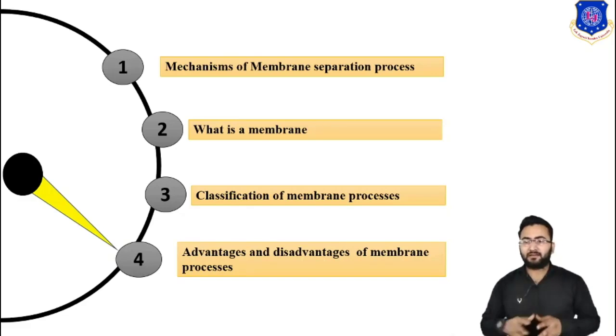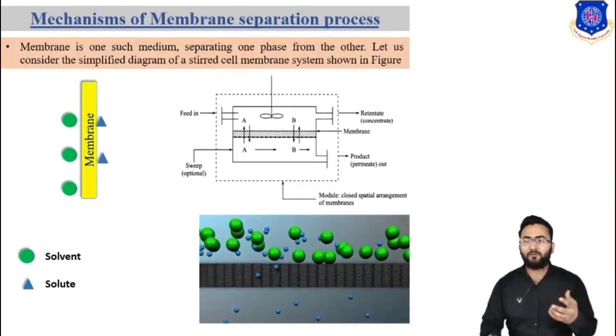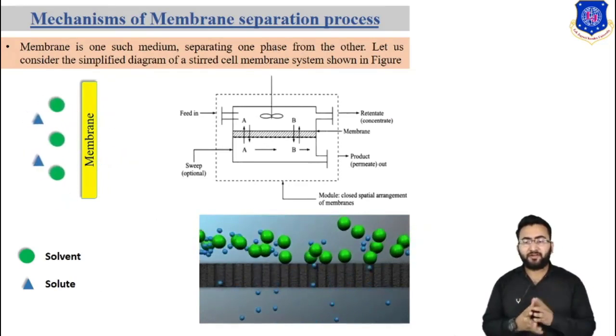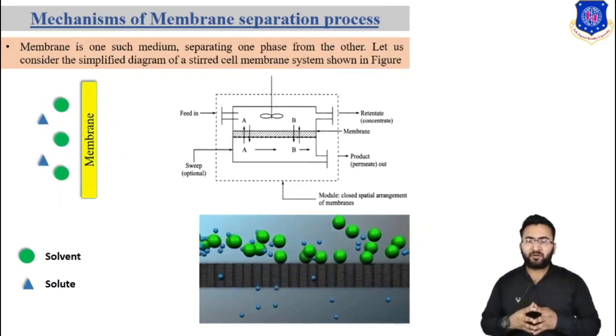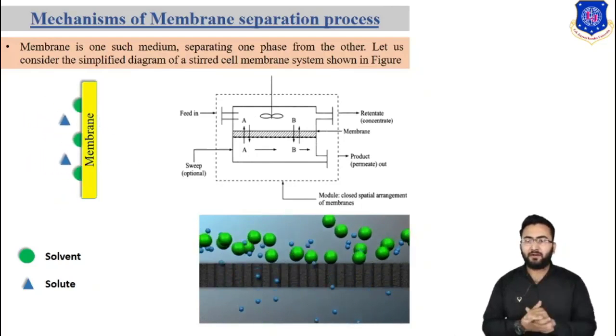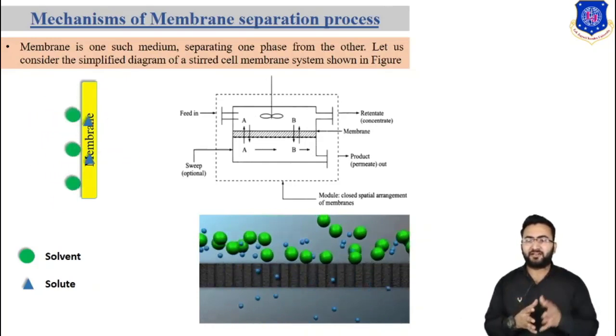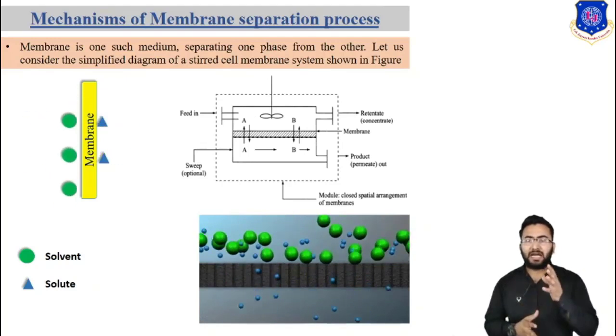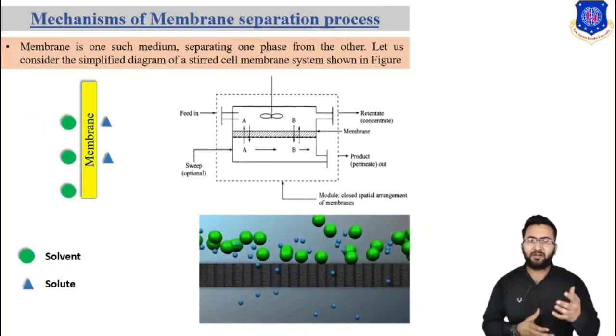So let us discuss the mechanism of membrane separation process. As discussed in the previous session, in general, separation processes of fluid mixtures can be divided into two categories: one, equilibrium separation process, and second, rate governing separation process. Conventional separation processes such as evaporation, distillation, extraction, adsorption and absorption, used on a large scale in industry, are based on